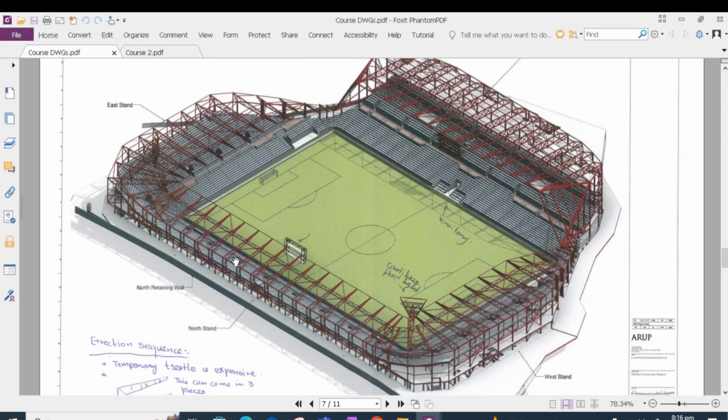We have the gravity load being transferred via the cantilever frames. The lateral load, on the other hand, can be transferred via the series of wind girder systems and the elevation trusses. As we can see, the whole system is braced in order to have a fully integrated structural system.